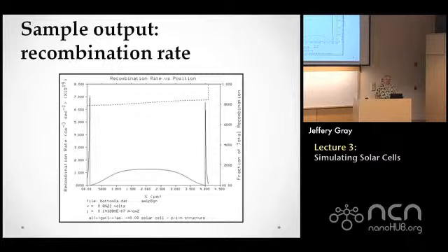But you really need to look at something else as well, which is how much that recombination contributes to the total recombination going on in the device, which is the dashed line here. And you'll notice that as that line goes through these points, it barely even budges, which means these spikes in recombination, which look like they're very important, aren't important at all.